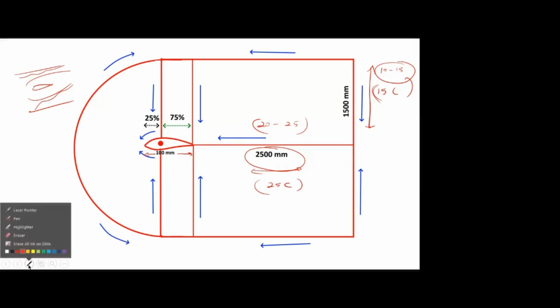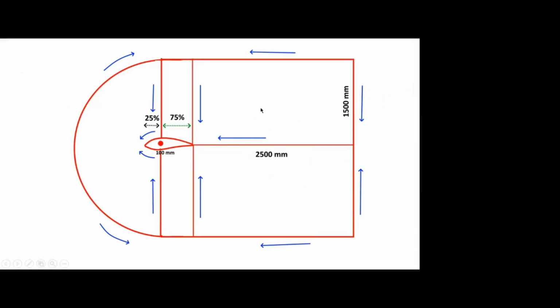And the blue color arrow mark shows the refinement. So here I am going to give number of divisions. In the previous experiment, simply we divided into equal number of divisions, right? For example, if you give 5 divisions, it will divide equally. But here I am going to use bias, another option in the division. Bias means we have to give another value, the bias factor.